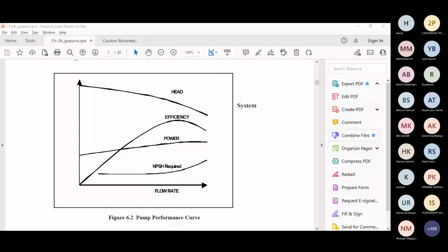The unit is always fixed. Correct? So actually, the pump supplier will supply the head in terms of the specific liquid, so he is specifying the pump head on the basis of that liquid. It's up to us, while we are changing the use or type of fluid, the head will be revised.